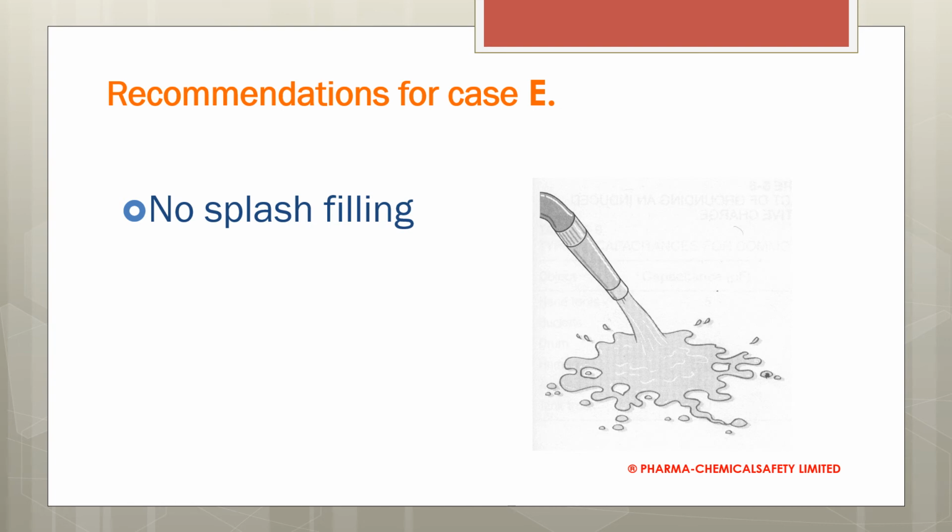The same applies to flammable liquids, but the LOC for flammable liquids is very, very low. Some have 6%, others have 4%. In this case, you have a high oxygen concentration. You are inert for sure, but you need to make sure that you are below the LOC of the flammable liquid, 40% if you have an oxygen detection system and 60% if not, to avoid this type of phenomenon.